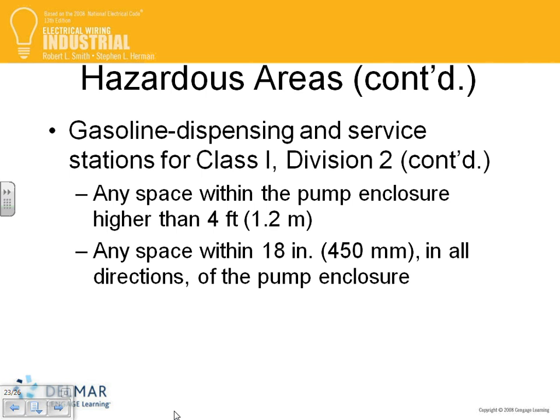Yes, sir? For something that's class 1 div 1, does it have to be serviced much more frequently? Does it have to be checked on? Is there a requirement like, this has to be checked every 6 months or something to make sure everything's okay? The NEC code doesn't talk about service. But I'm sure there's probably something for the gas station. There's an NFPA, yeah, I'm sure there is. But not in NFPA 72 or in the NEC code. I'm sure there's an article that tells you that you have to check them more frequently. Not the NEC code though, that I know of.